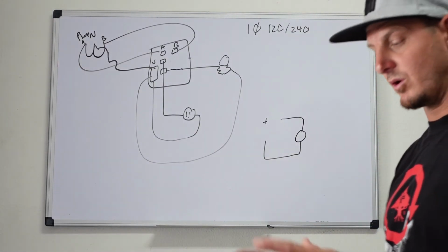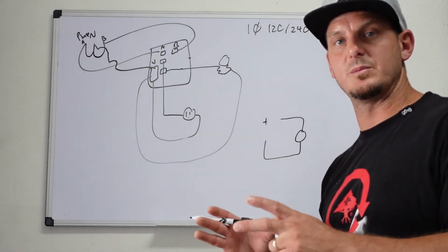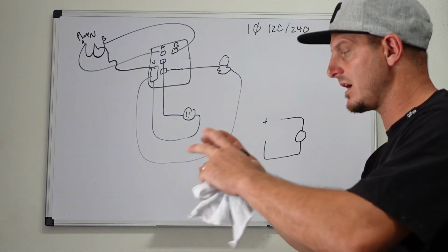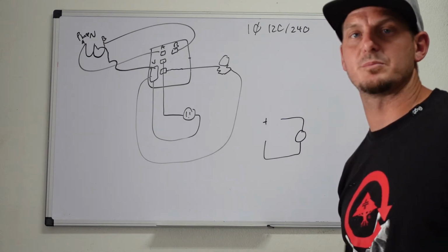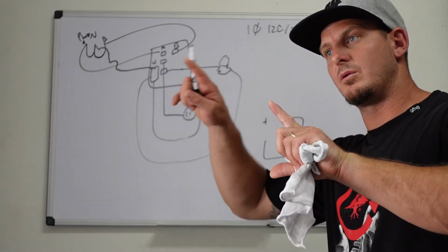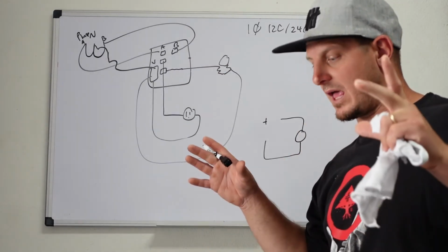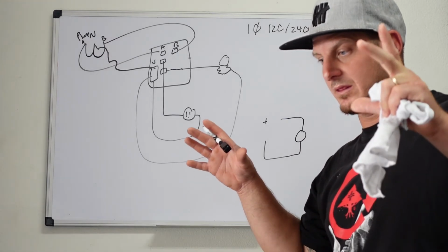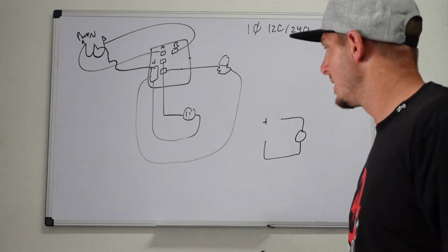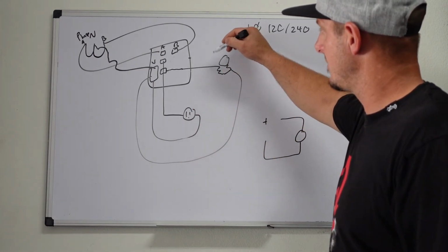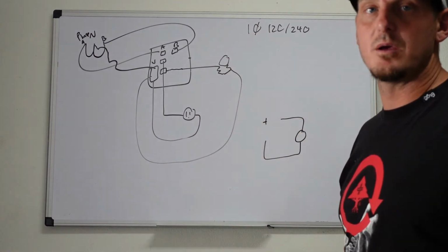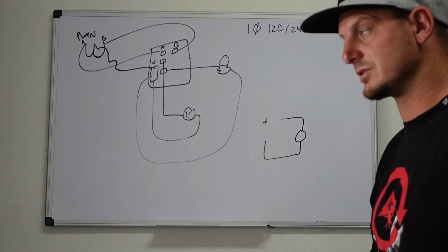But that doesn't mean the whole system is series, because if you have any other loads off that phase, it then becomes a parallel path, meaning more than one path is available, and it changes. So instead of it just being a 120 volt drop across this, you would then have 120 volts here and here, because it is now a parallel circuit.